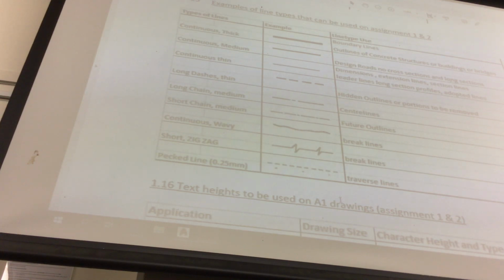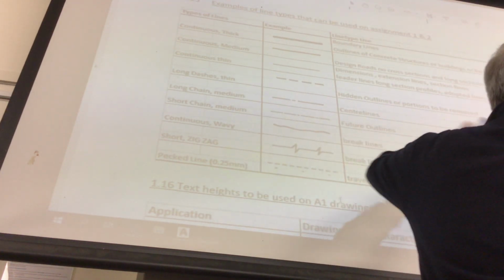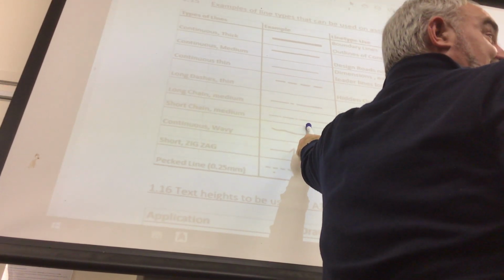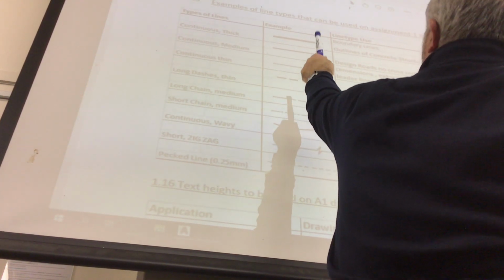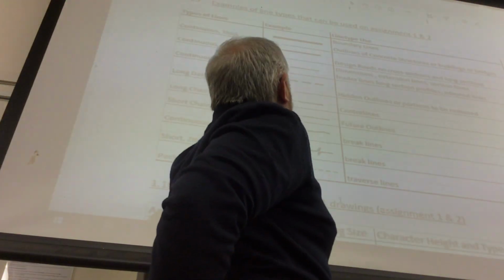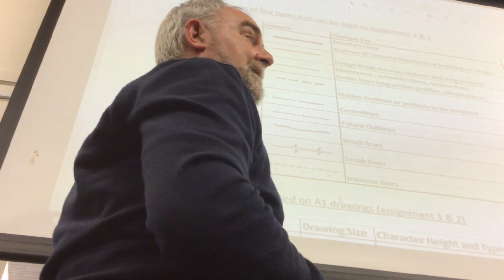And there's my famous pink line that I talked about. That's what the survey traverse should look like. Anything hidden should look like that. You'll need another line for, I showed you that drawing with the shed on it. The student should have put that line type on there, but they didn't. They just did another hidden line type. Centre line for the centre line of the pipe, hidden for the outside edge of the pipe. Boundary lines would be thicker if you find one there. If you don't find one there, you don't need to worry about that. Most of the line types will be like that for your continuous drawing. I think buildings and concrete type things should have a thicker, heavier line.